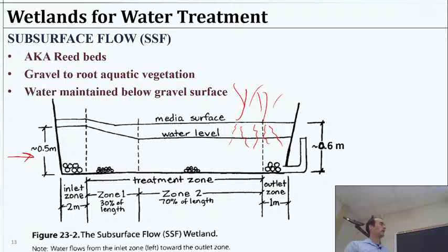So you've got the plants themselves benefiting from the nutrients as much as they can extract from the water. They'll be drawing out the nitrogen, the phosphorus, things like that. Lots of space for contact in this gravel media, and you can expect oxygen transfer to be decent because these are chunks of gravel. So there should be some aeration just simply by exposure, especially if we end up draining it.